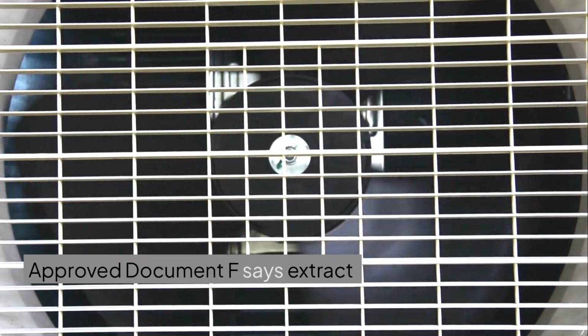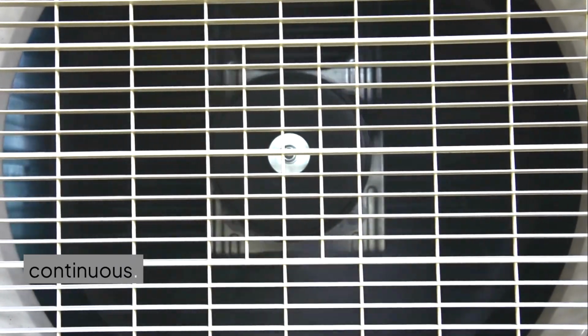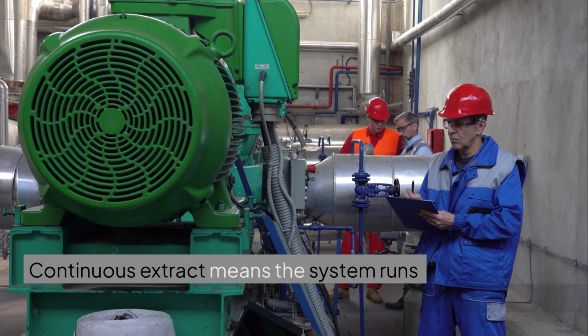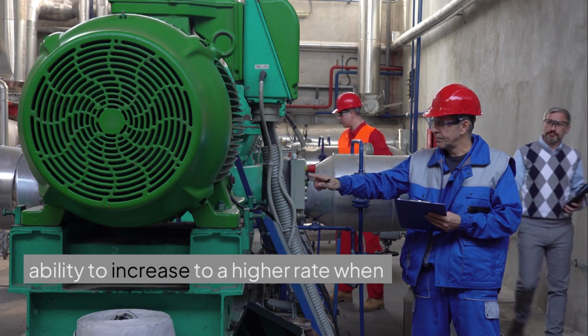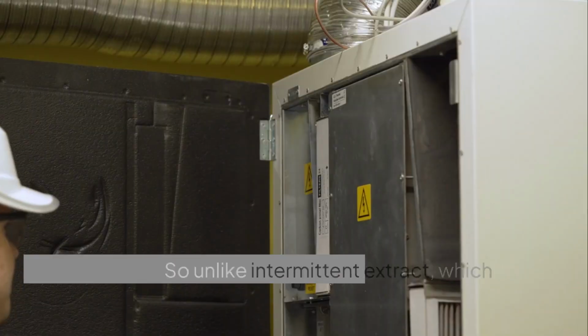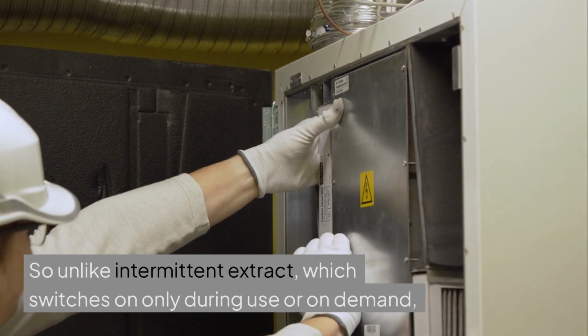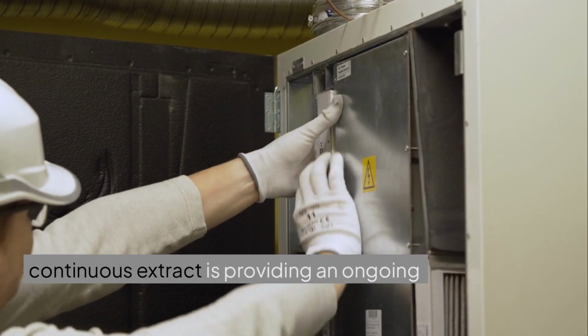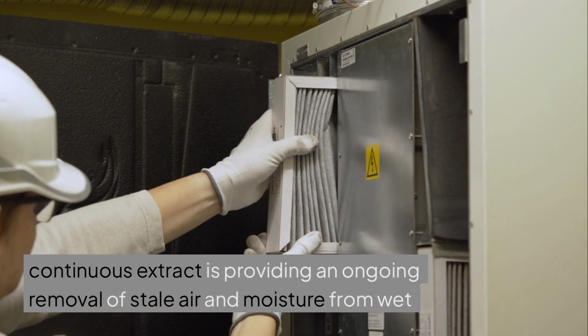Approved Document F says extract ventilation can be intermittent or continuous. Continuous extract means the system runs all the time at a background rate, with the ability to increase to a higher rate when needed. So unlike intermittent extract, which switches on only during use or on demand, continuous extract is providing an ongoing removal of stale air and moisture from wet rooms.